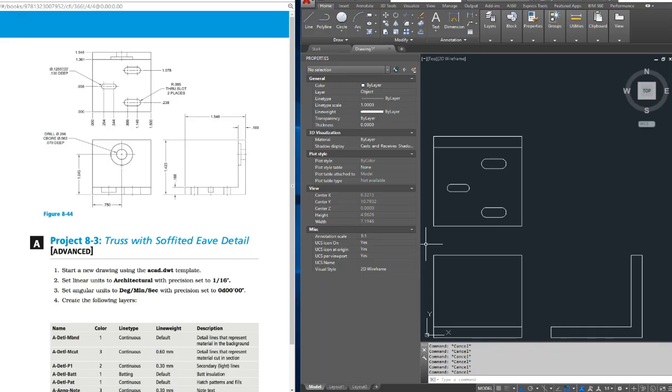So here we go. I'm going to draw that circle. I'm going to say offset 0.75 from here to here, so I can find my center, and offset 1.045 from the bottom up. That's it. So now I can just worry about my two diameters.